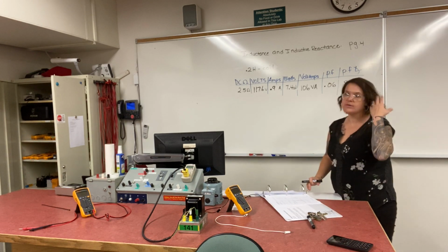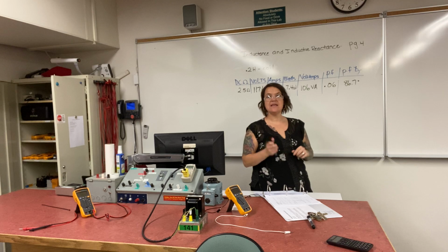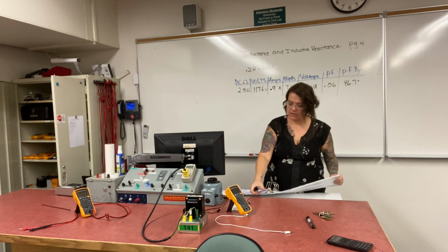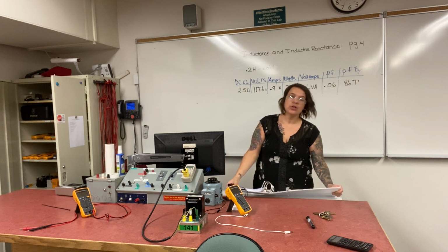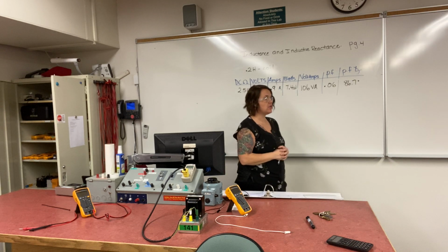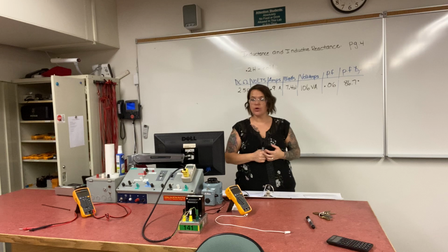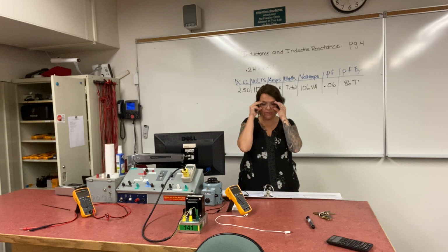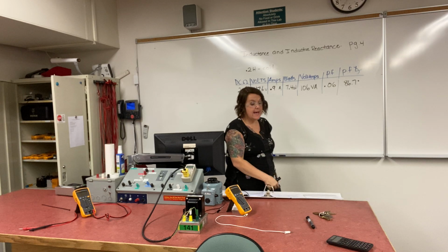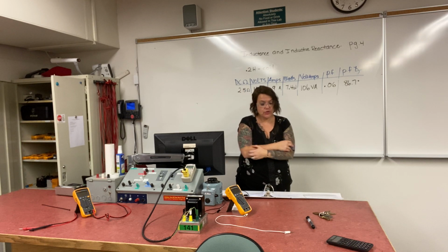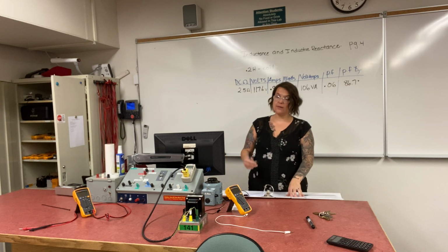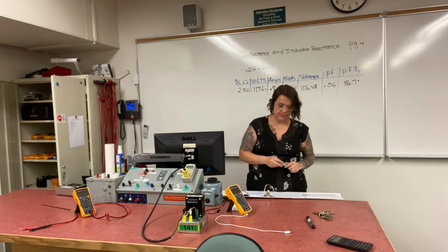So it talks about Z coil. Z is the impedance of the coil. When you're dealing with AC circuits, we no longer use resistance in conjunction with Ohm's law to solve for the overall current, because we are not just dealing with in-phase loads any longer. We are dealing with coils and motors. So we have to use the formulas given using impedance, not resistance.